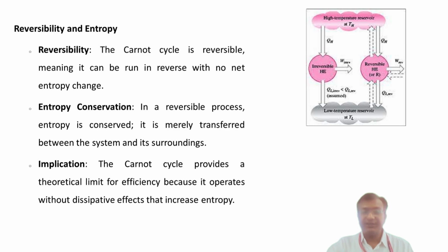Now, in real heat engines the processes are not reversible. There are always some irreversible steps such as friction or heat transfer across a finite temperature difference, which leads to an increase in the entropy. This means that for a real engine, the total entropy change for the cycle is greater than 0, indicating that some energy has been dissipated as heat, reducing the engine's efficiency. The Carnot cycle, being reversible, has no such dissipation, hence its efficiency is the maximum possible.